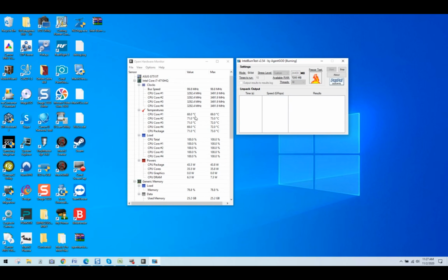So you can see here how we're climbing steadily. Temperature goes up, goes down, and then you'll just see it keep climbing. Processor usage will keep fluctuating, and the wattage will keep fluctuating. Once again, if you look at our memory load as well, you can see it's also going way up, and that's exactly what we want. Because the overall goal here is to make your computer as stressed as possible, more than it ever will be, because once you load Mach 3 or Mach 4, regardless, CNC, Centroid, whatever motion control software you want, we then have that peace of mind to know the system is stable.